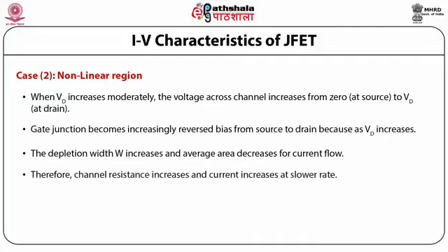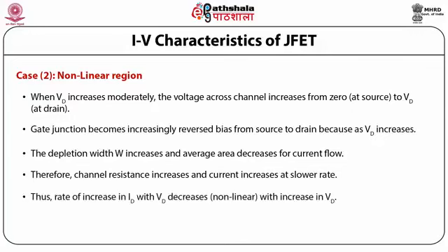Therefore, channel resistance increases and current increases at a slower rate. Thus, the rate of increase in Id with Vd is nonlinear.